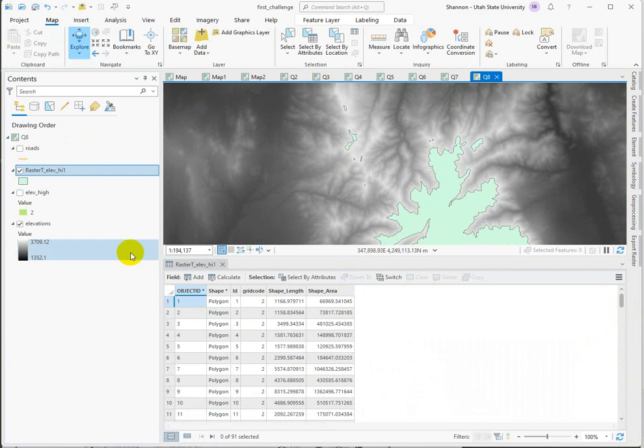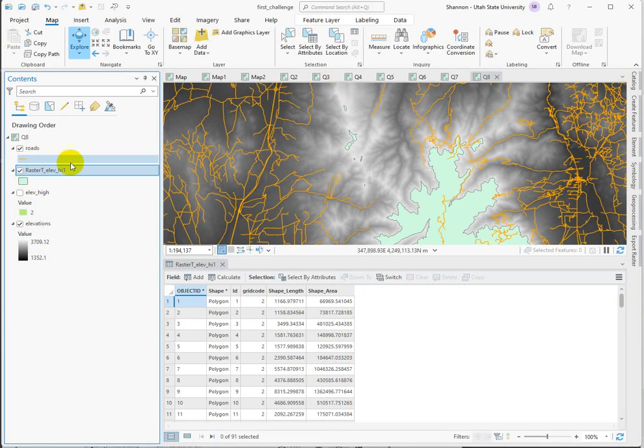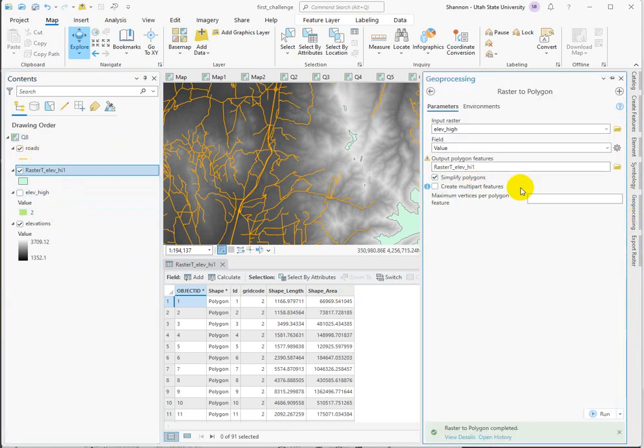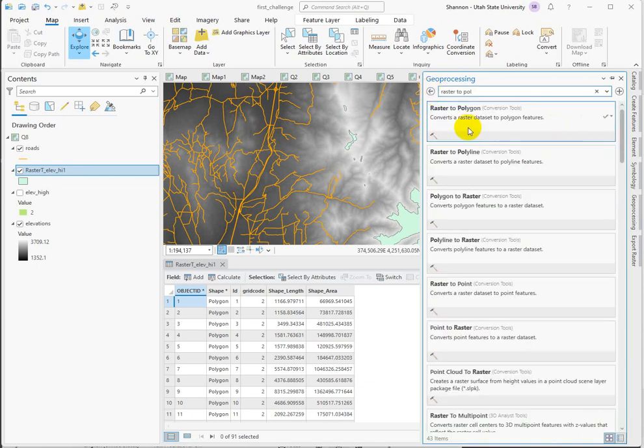All right, so we could either pull out our roads by speed limit now, or just go ahead and cut it and then pull out the 65-mile-an-hour roads later. I'm just gonna go ahead and cut it. So I'm gonna use the clip tool because that's the one that acts like a cookie cutter. I don't need to preserve the name of each one of these polygons. I'm going to treat them as just one entity, and so clip works perfectly. And it's the analysis version.